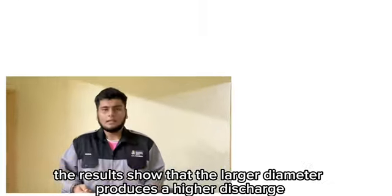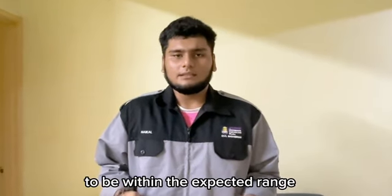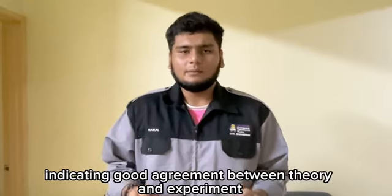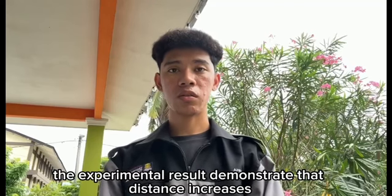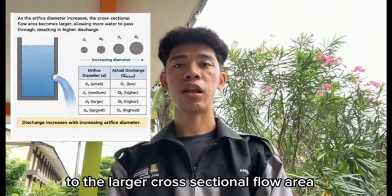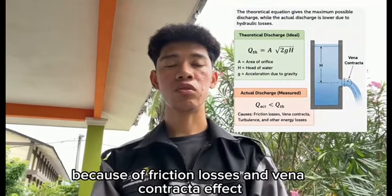The results show that the larger diameter produced a higher discharge due to the larger flow area. The calculated coefficients of discharge were found to be within the expected range reported in hydraulic engineering literature, indicating good agreement between theory and experiment. For discussion of results, the experimental results demonstrate that discharge increases with increasing orifice diameter due to the larger cross-sectional flow area. Although the theoretical equation predicts the maximum possible discharge, actual discharge remains lower because of friction, losses, and vena contracta effect.